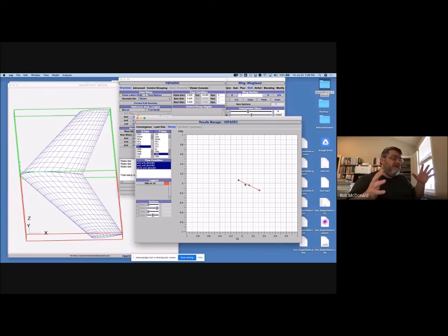And in that trim, if you want to go a little faster or you want to climb a little, let's say air traffic control comes on and says, hey, would you climb and speed up? You don't even have to touch the yoke. You can just reach down to the throttle and say, okay, I'm going to move the throttle forward a little, and you're going to start climbing. And if you need to speed up, you can roll in a little more trim. You can put in some nose down trim, and the airplane will start to speed up. You don't even have to touch the yoke. You can do it all through the trim controls. And it's all about adjusting this very subtle equilibrium.